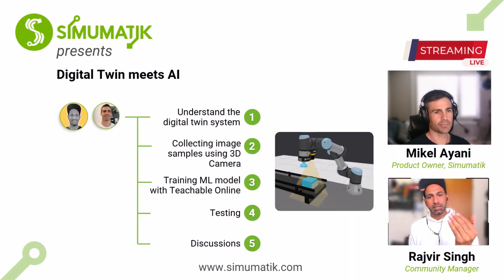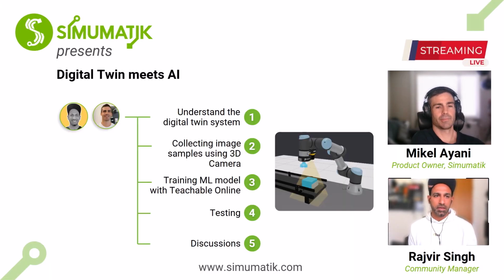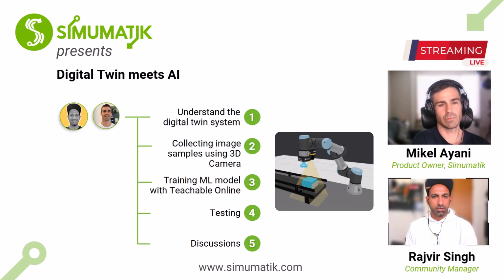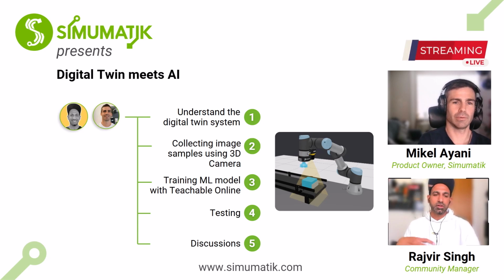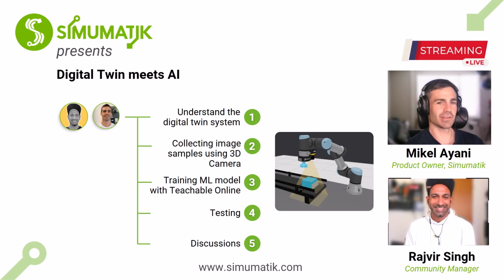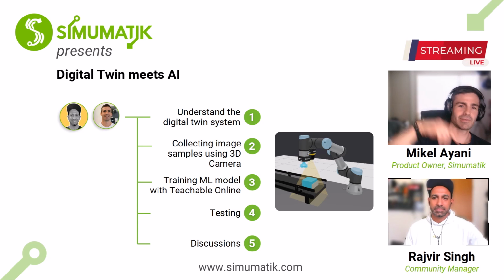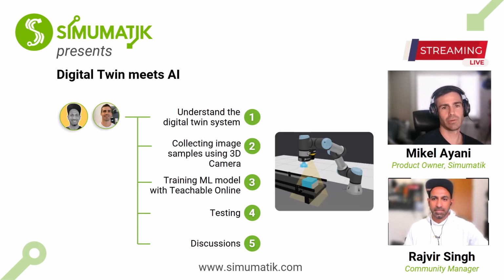And then I get the result back from the cloud, bring it to my Raspberry Pi, and then the Raspberry Pi sends the result via OPC UA back to my CODESYS, and CODESYS sends the result to the robot. So it's a lot of things happening. Yeah, it's a lot of systems going on. So you have a model running the camera and the robot and the conveyors and the boxes. You have URSim to control the robot, CODESYS to control the PLC, and then you have the Raspberry Pi with Node-RED sending pictures to this Google service. Yes, an AI kind of thing.